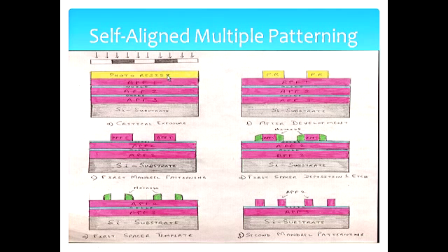This is the first step. This is your mask on which you have your critical dimensions defined. These are APF, it's called advanced patterning film. It's a commercially available material that is used in this process. There are 3 layers. This is your silicon substrate on which you want your final pattern to go, but there are 3 layers before that.